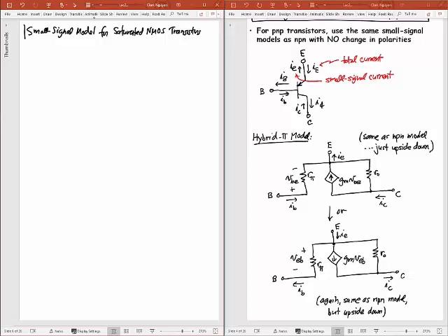And so I should mention that everything that I've done for the bipolar transistor has been forward active. Like I said before, for analog circuits, forward active is where you're always operating the bipolar transistors. For NMOS transistors, for analog circuits, generally you're always operating them in saturation, or in linear, like you saw in your previous lab number 3, I think it was. And I should say right off the bat, this is for analog applications.